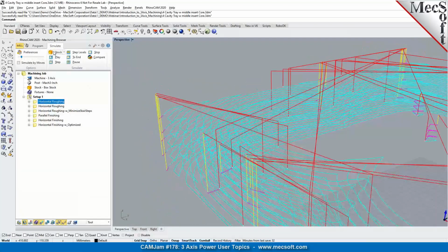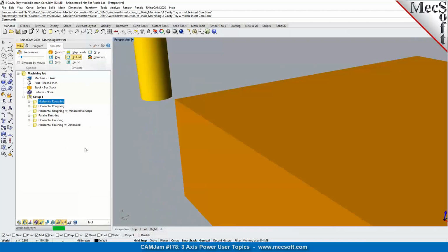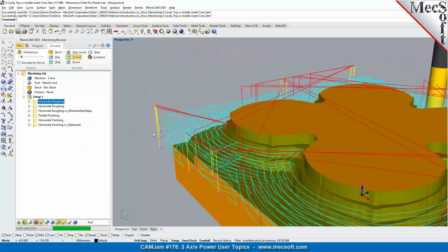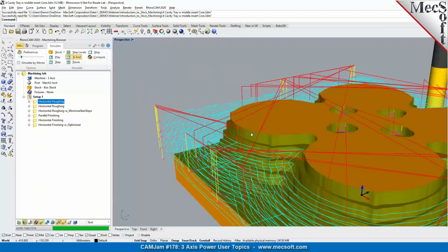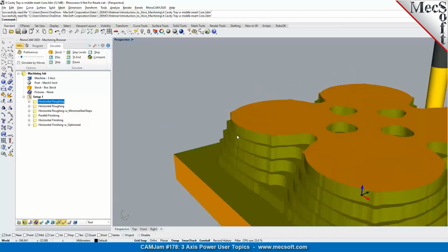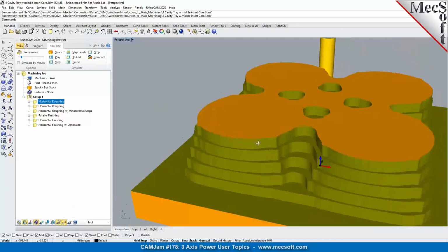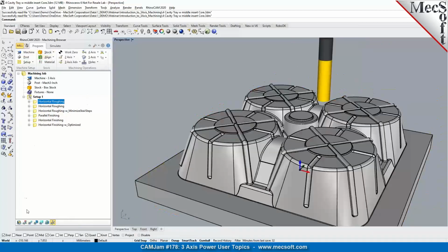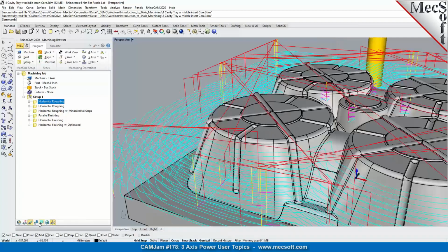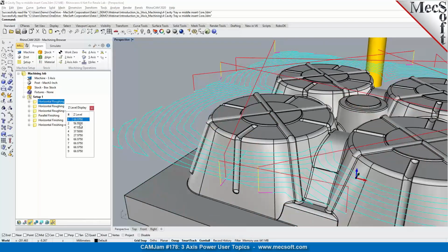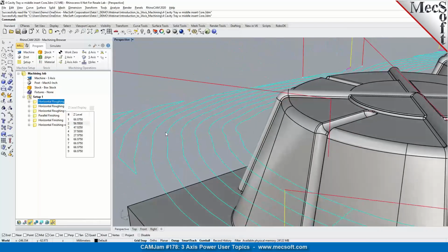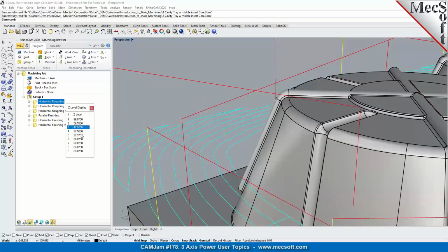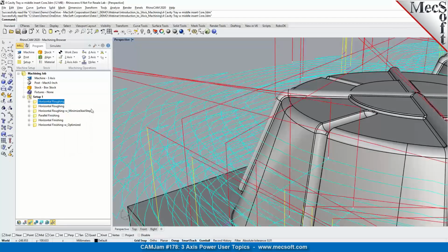So as we generate and simulate the toolpath, I'm going to run simulate to end, which is running through it, and you'll also notice the facets and the effect of the tolerance on the rough part in here. Now, as we go back and tighten up these tolerances, I'm going to step through the levels before I tighten up the tolerance. So you can see for each of the levels, the chord segments are much farther apart based on the tolerance settings that we put in.